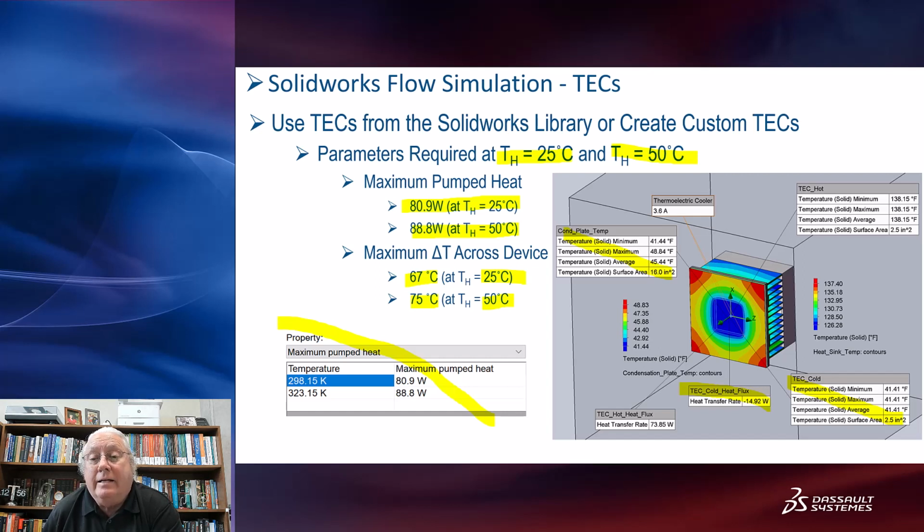And the last thing to look at is this. This is the operating amperage. And so, again, when these thermoelectric coolers are operated, depending on lots of parameters, including the hot side temperature and the amount of heat that you're trying to move, it adjusts and predicts, simulates, what that current would need to be to operate in the ranges based on those values we put into the thermoelectric cooler device in SolidWorks Flow Simulation.